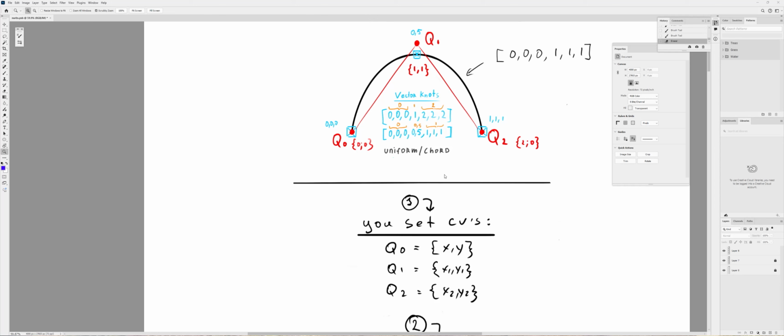So these values, like 0, 2, 35, 37, are not just numbers in the vector node which will be squashed into the parametric space uniformly. These are the actual lengths of your curve and where the edit point is supposed to go. This is geometric. So we are actually spreading the values on the domain based on the actual distances.